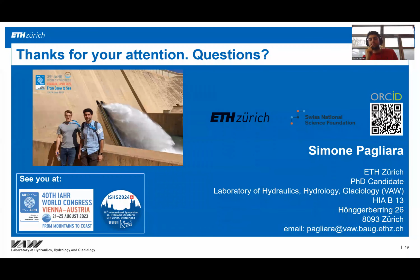And then on the upper limit, you have the energy over which a bubble of a determined size penetrates the free surface. In your scale models, I imagine you will be working on the very high end of the spectrum, meaning that since you are forcing the entrainment of air with the gate, you are working in the very high turbulent regime of air entrainment.